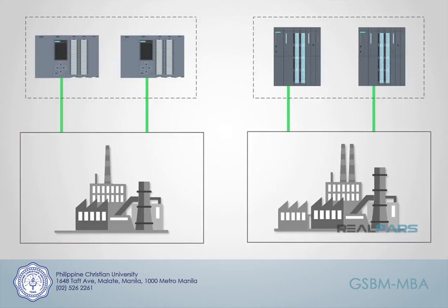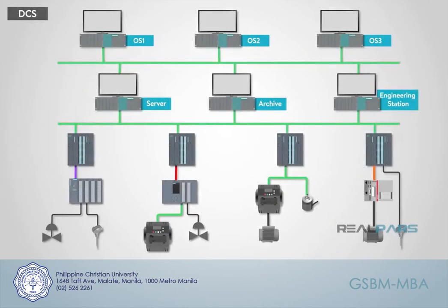Just as there are circumstances for a PLC system, the use of DCS would be for larger, more complex processes that require a lot of interaction between many processors. Now that we've touched on some of the differences in the systems, let's focus on the DCS and some of its components. The DCS is a process-oriented system that uses closed-loop control.